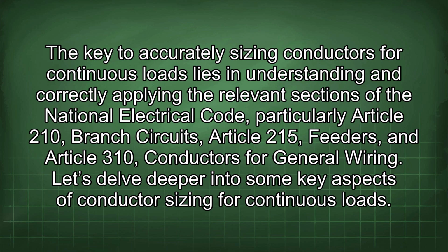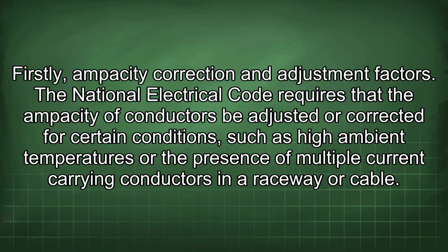Let's delve deeper into some key aspects of conductor sizing for continuous loads. Firstly, ampacity correction and adjustment factors. The National Electrical Code requires that the ampacity of conductors be adjusted or corrected for certain conditions, such as high ambient temperatures or the presence of multiple current-carrying conductors in a raceway or cable.